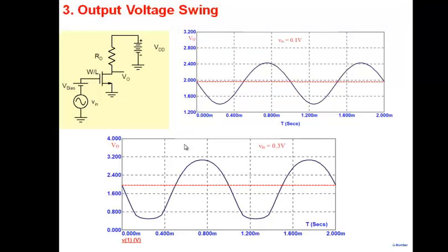it appears to be a reasonable sinusoid, right? But it's not the visual check which you should perform. What one can do is take this waveform and do, let's say, an FFT on it, which will give me a spectrum. What you will find is that this is not a pure sinusoid. I will see that apart from a fundamental, there's a second harmonic also. So distortion is always there.